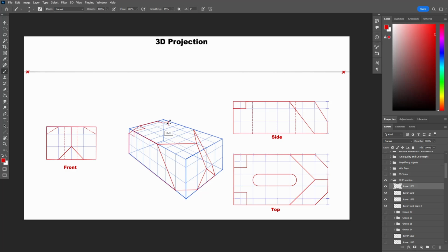Now all is left is adding the hole in the center, which isn't an ellipse, but more of a smooth rectangle. To do this, let's first draw the bounding rectangle, 1.5 unit in and 3.5 unit long, with 1.5 unit space on the other side.